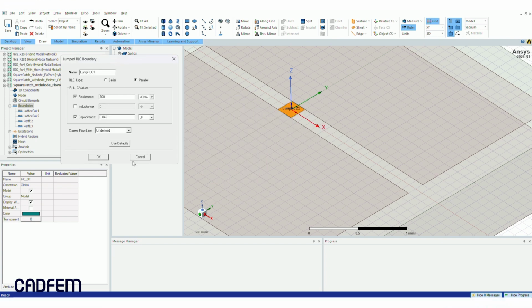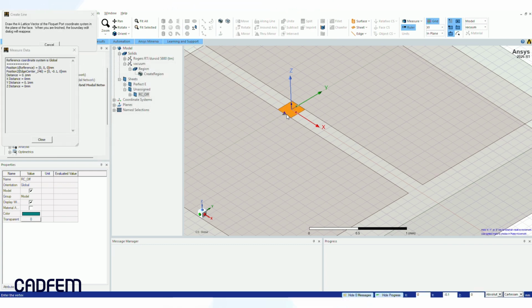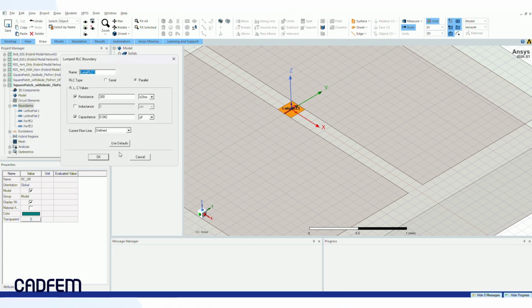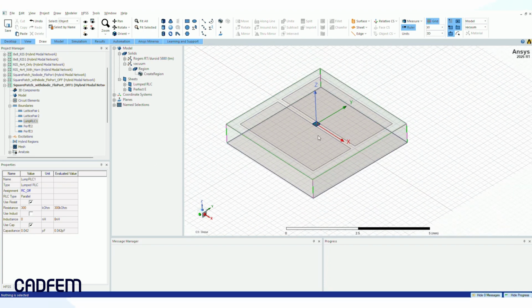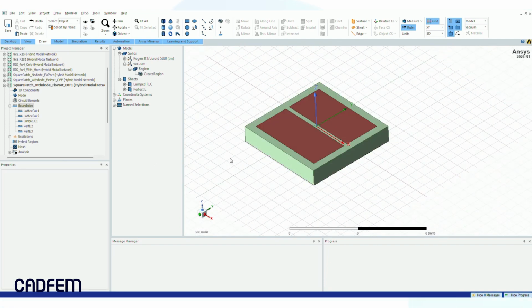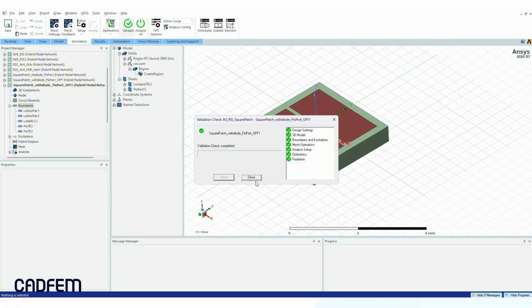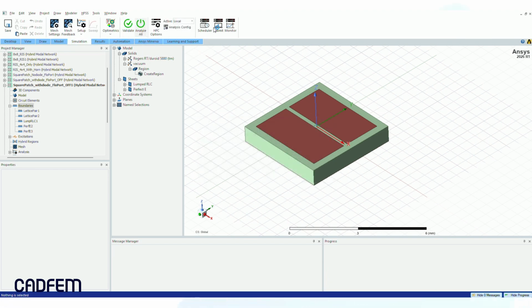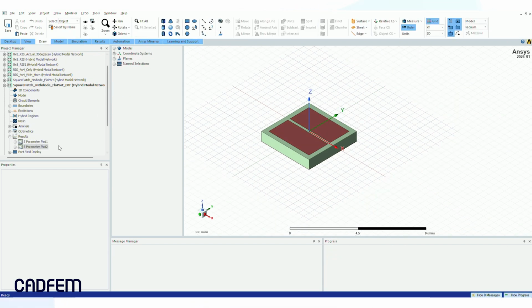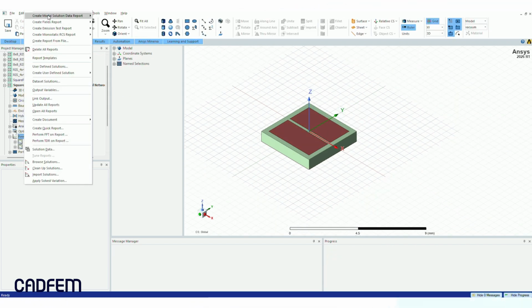Accurate vector placement is essential, as it determines how the Floquet modes are referenced throughout the simulation. This ensures that the incident wave interacts with the periodic structure in a physically consistent manner. With the Floquet port fully configured, the model is now prepared for the excitation and analysis of electromagnetic wave propagation through the RIS unit cell. We advance through the remaining default setup wizard options to complete our primary Floquet port initialization.